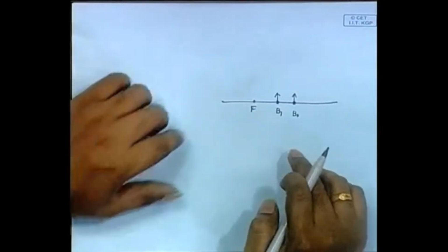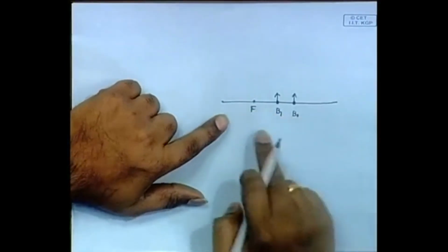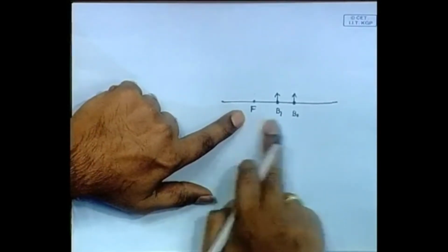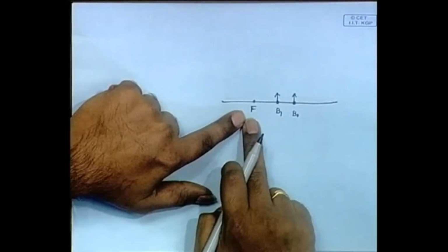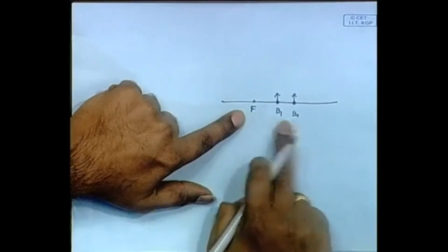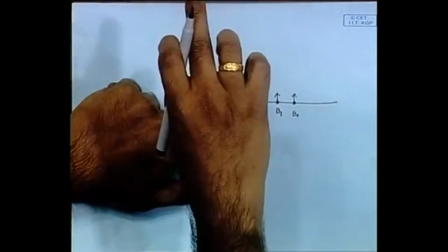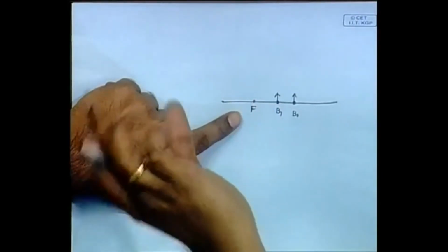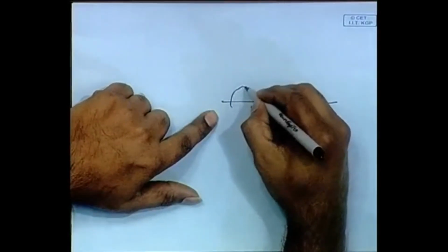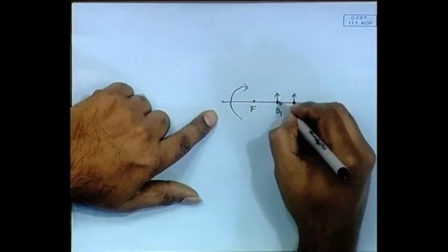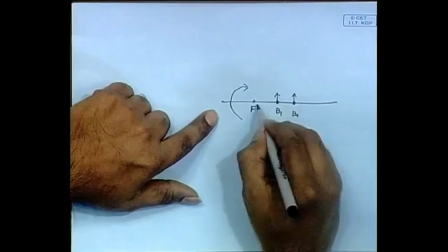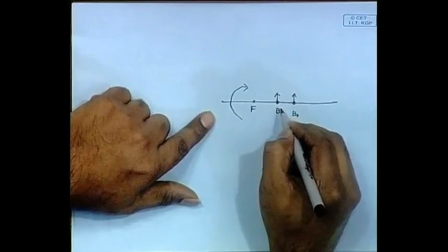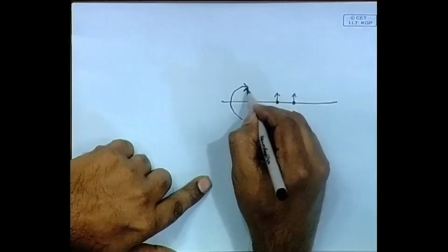See, that is initially, okay, look at this figure. Initially it says that F is the center of flotation. Initially F, obviously you have to take the moment about F because it's trimming by F. So F into this distance, FB0, this is the initial, it is higher. In this case it's lesser, okay. So the moment is decreased. That is a better way to put it. The moment is like this initially, the moment is lesser because the distance has decreased. So that means it's like a reverse moment acting like this, okay.